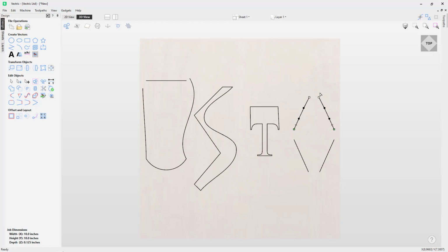Now, if I press H on the keyboard, a line appears, and that is a line to indicate horizontal mirroring. So what will happen here is if I press the left and right keys on my keyboard, you'll see how the nodes move together because they're mirrored. That line in the middle represents a mirrored line, and you can see how you can node edit mirrored with this option.